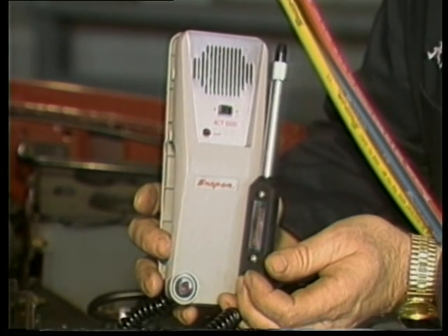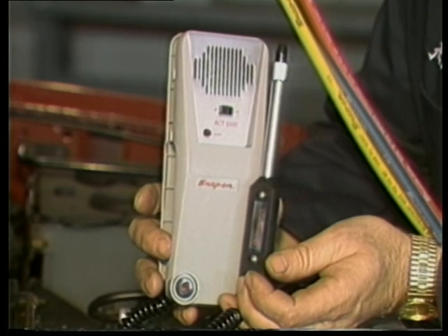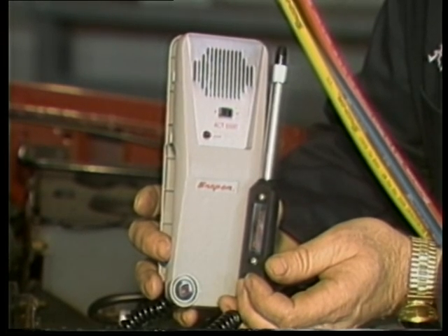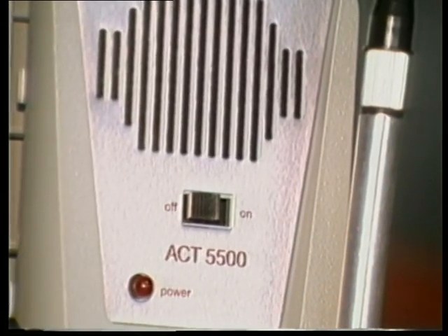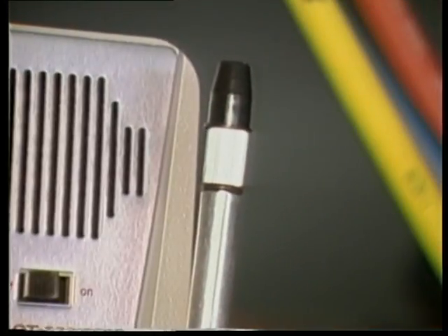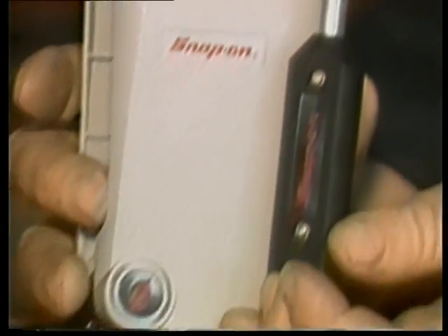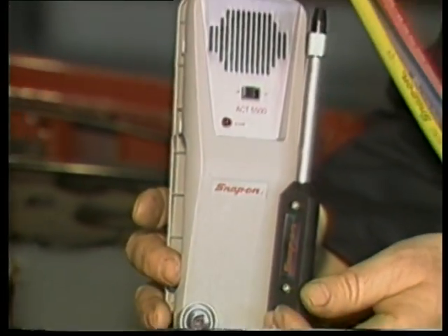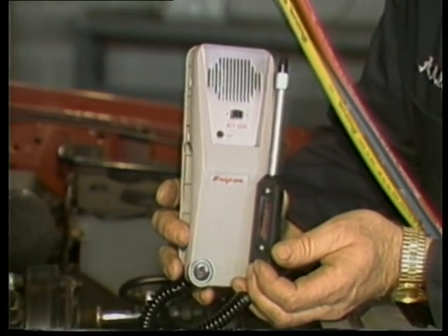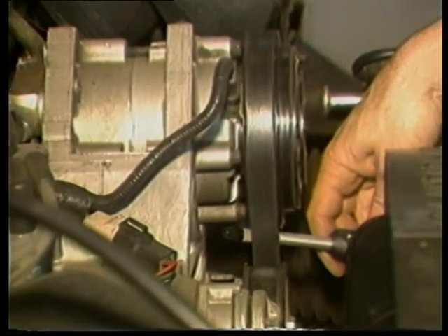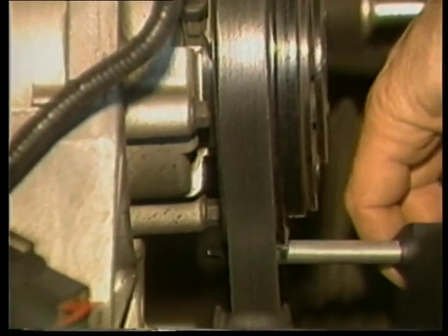An electronic leak detector is commonly used to find refrigerant leaks. It will make an audible change in tone when refrigerant is present. It uses an internal sensor to trigger an amplifier circuit to operate the speaker. An electronic leak detector is the fastest and safest way to locate system leaks.